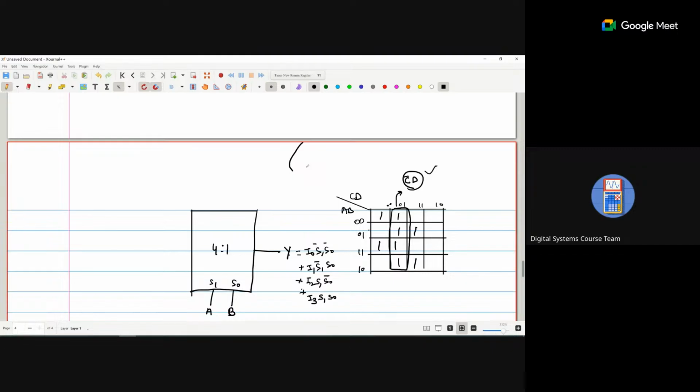This is the problem. What's the issue with using the K map? If we create a group where the terms A and B are not available, how do we implement that term using the multiplexer where the select lines A and B are fixed?